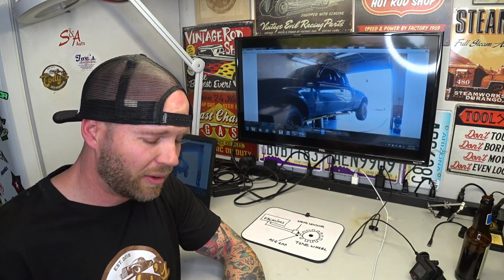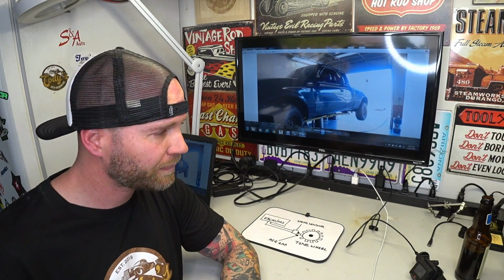Ended up getting front and rear brakes. They were metal on metal front and rear, or pretty close to metal on metal. They needed replacement. So what we ended up doing is we replaced the front rotors because they are out of specification, so we weren't able to turn them. Replace the front rotors, replace the seals, also replace the bearings. There was some pitting on the bearings. Replace the rear brakes, the shoes, turned the drums, replaced the hardware, and also performed a brake fluid flush. There was some moisture in the system.